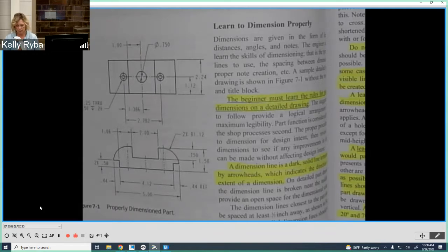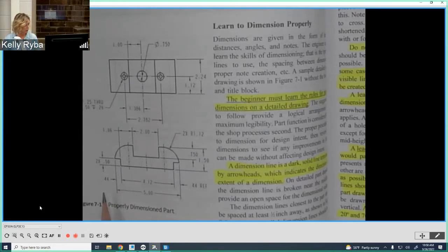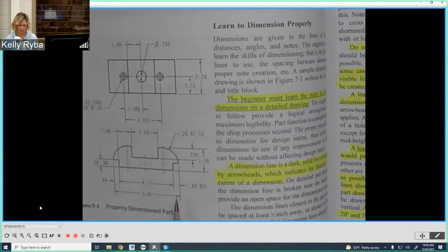There is probably one criticism that I have on this particular drawing. One of the rules, and this is in the ANSI standard, is that every dimension needs 2 arrowheads, okay? Sometimes people do this because they think it looks nice and they're saving space, but actually it's not to the standard. You'll notice here when we look at these 3 dimensions all in line with one another, do you see how they don't have 2 arrowheads for the 0.44 on the left or the 0.44 reference on the right? Now, adding reference on the right is totally fine, okay, but we should scooch these up or down so that they both have their own 2 arrowheads for that dimension.